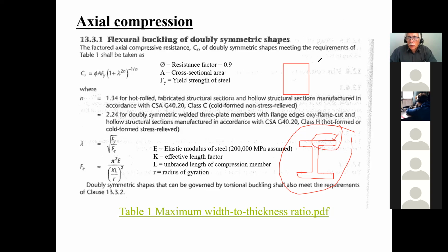In wood, not a problem. I know that it's always going to be the overall section that's going to give me my resistance. But in steel, you have to check if I'm going to rely on this whole area here. Like in other words, see here, A, that means I am relying on this whole area to give me my resistance. And that's assumed that the whole thing will eventually get to that yielding point. But if this is too thin, this thing can buckle before my whole area will contribute to the resistance, and therefore the member is still going to fail.